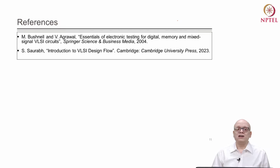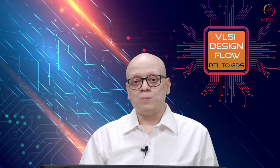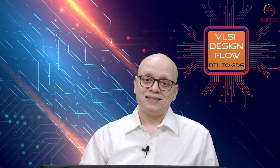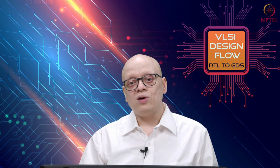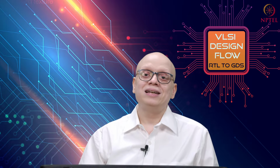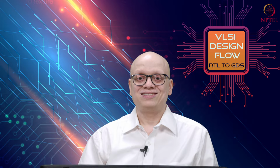And just to summarize what we have covered in this lecture, we have looked at what design changes we need to make to implement scan design flow, what the mechanics of scan design testing are, and what design tasks we need to carry out to implement scan design flow. So, in the next lecture, we will be looking at how we can generate the test patterns to test our chips. Thank you very much.